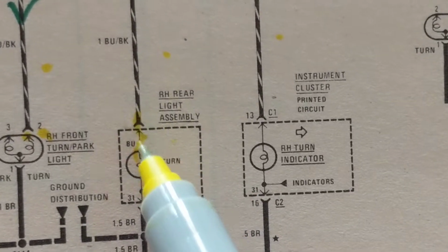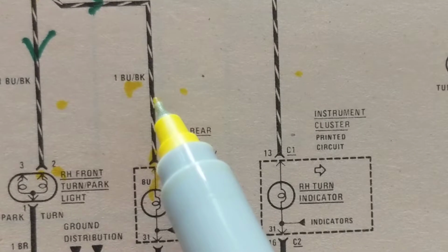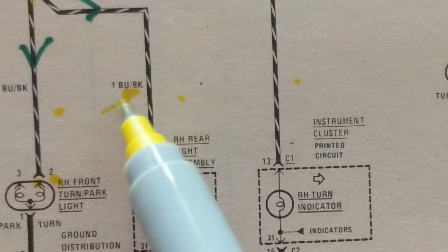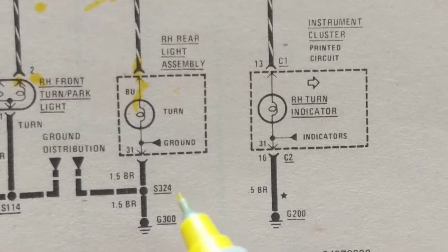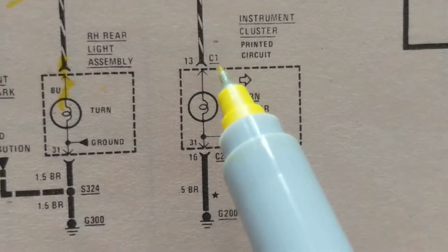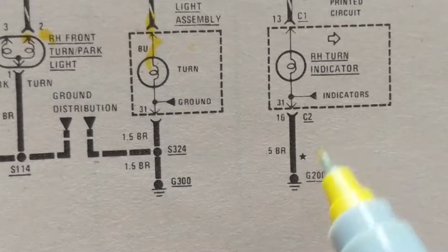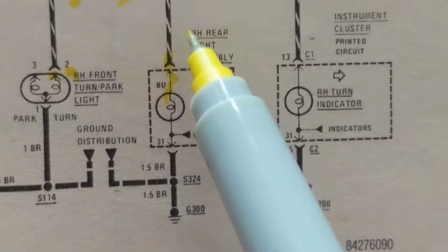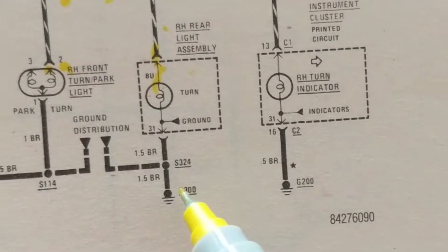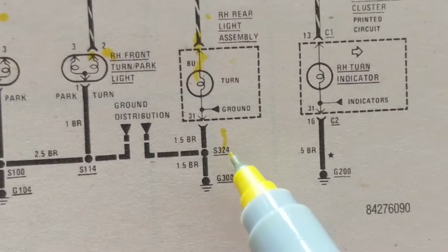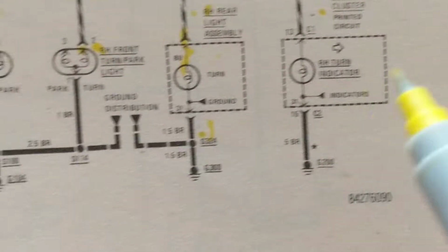This is to the bulb. This one. To the brown or black wire. As you see over here, it says connector 1, connector 2. And therefore, this goes to ground. If there is no ground, this will be open. This might be 12 volts, or this might be 12 volts. Ground pulls it down to 0 volts. So 12 volts here, 0 volts here. 12 volts here, 0 volts here.